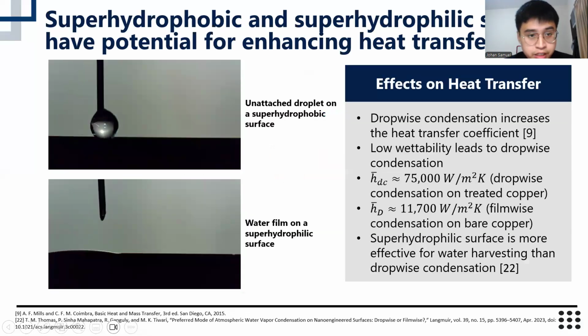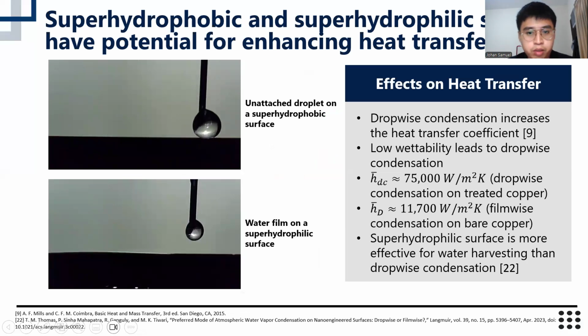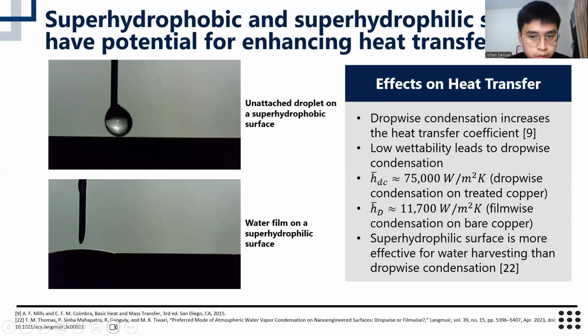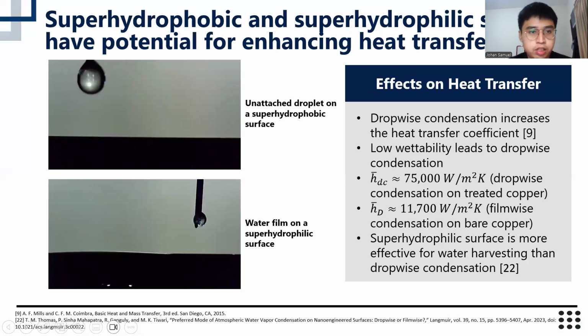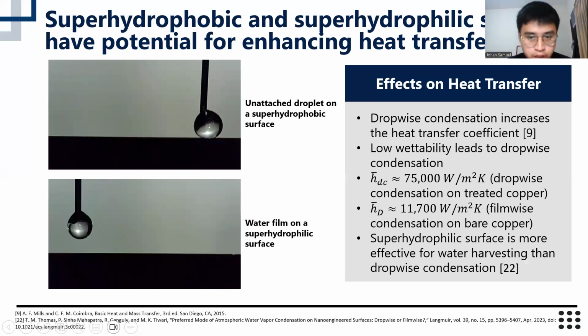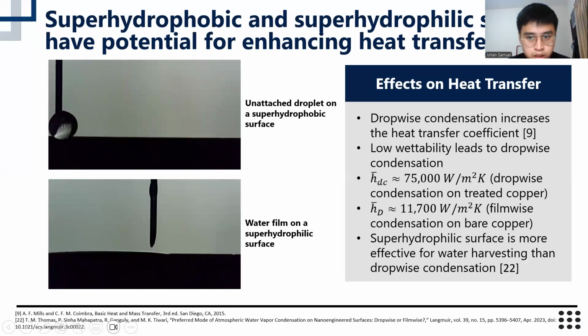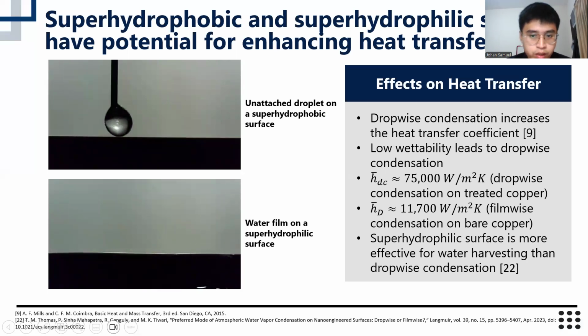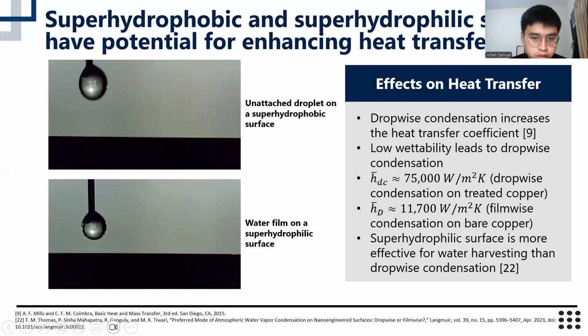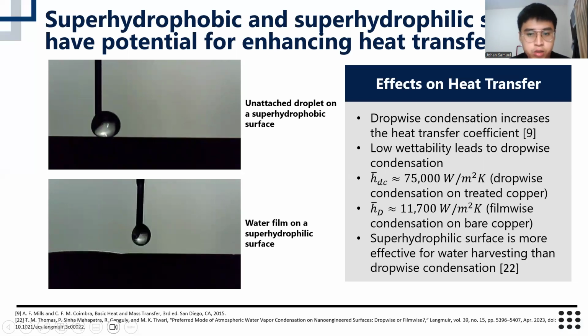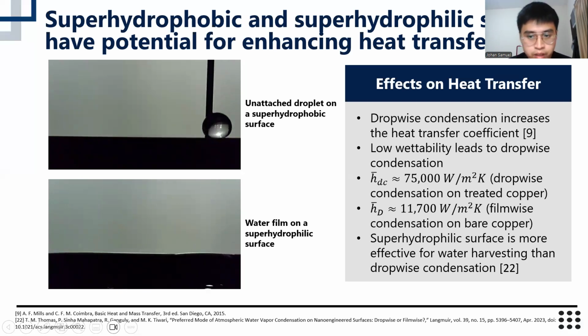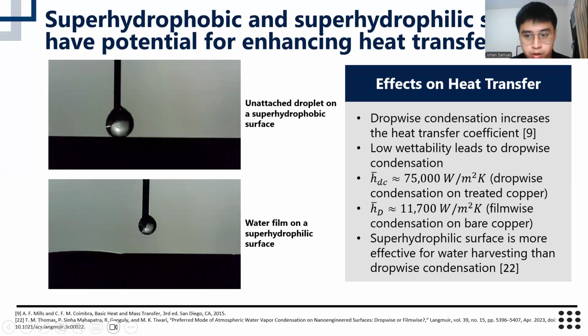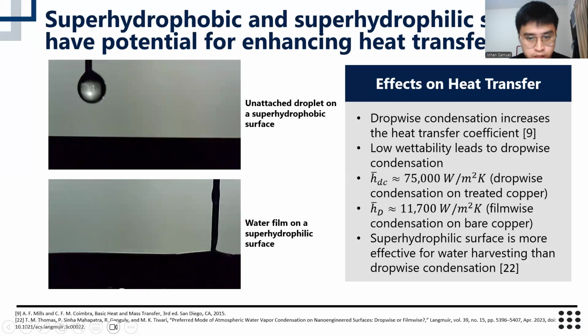As we can see, the video shows the wettability of superhydrophobic and superhydrophilic surface, and the wettability indicates how easily a liquid sticks to a solid surface. To have superhydrophobic characteristic, we would like to have a low wettability. It is done by lowering the surface free energy, since surface energy refers to the energy needed to create a new contact surface area. In this case, it is done by applying a silicon polymer called PDMS, or polydimethylsiloxane.